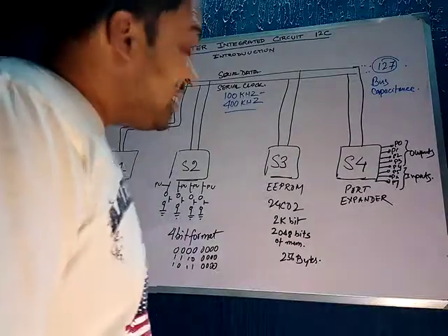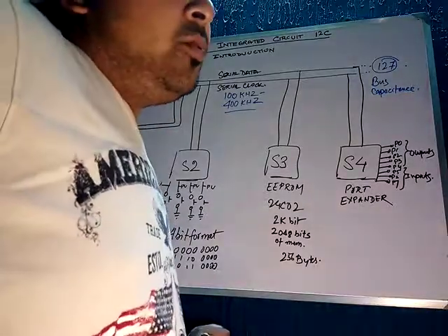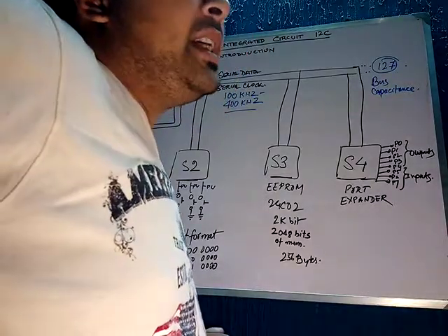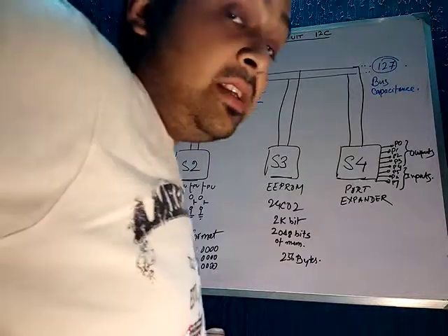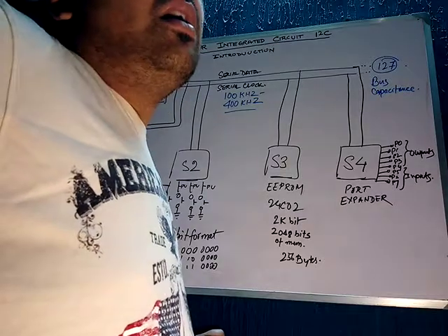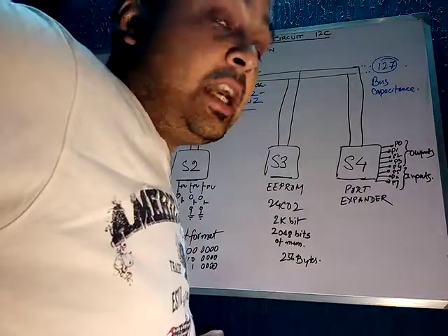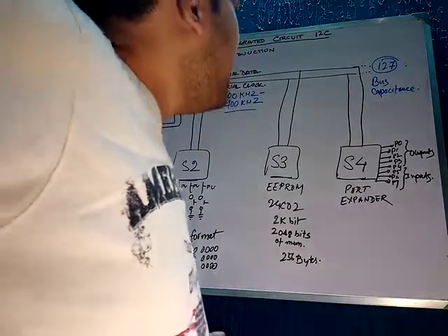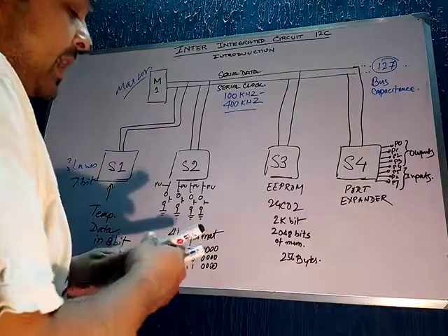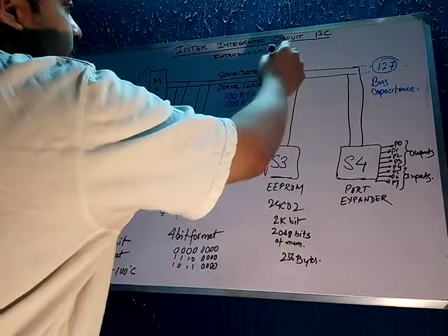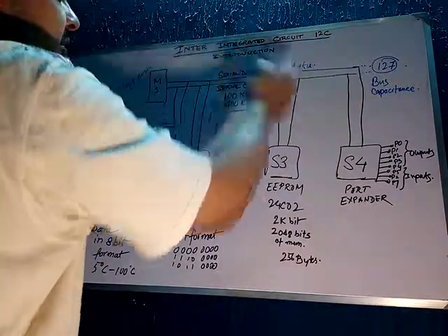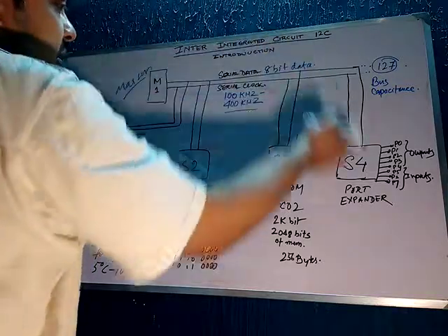I2C communication. But let me tell you, Texas Instruments have been able to develop I2C communication with 10-bit addressing, not 7-bit, and a 1 Mbps super I2C communication line. But all those things are very complicated. I will not bring them up right now. We'll study it later on. And the data will be 8-bit data that will be sent from the slave to the master or from the master to the slave.